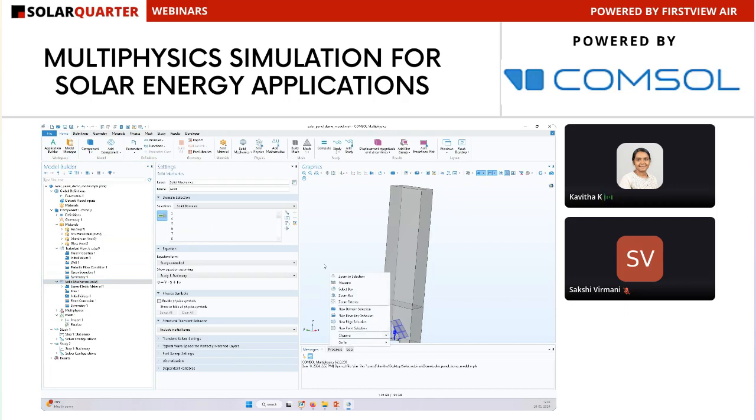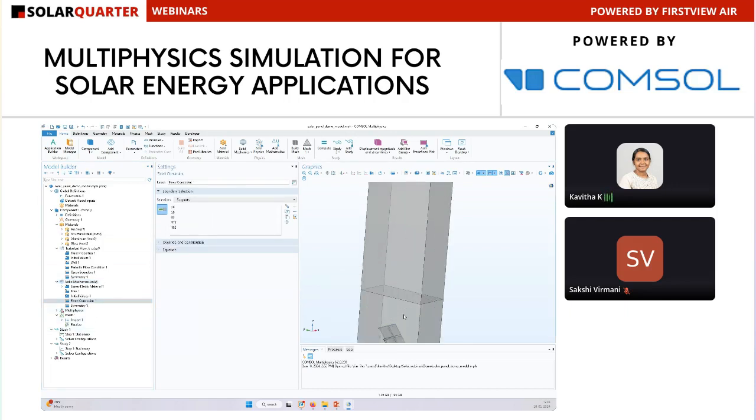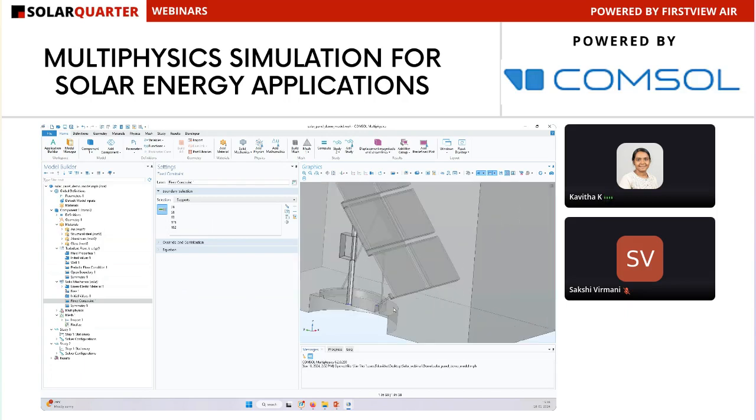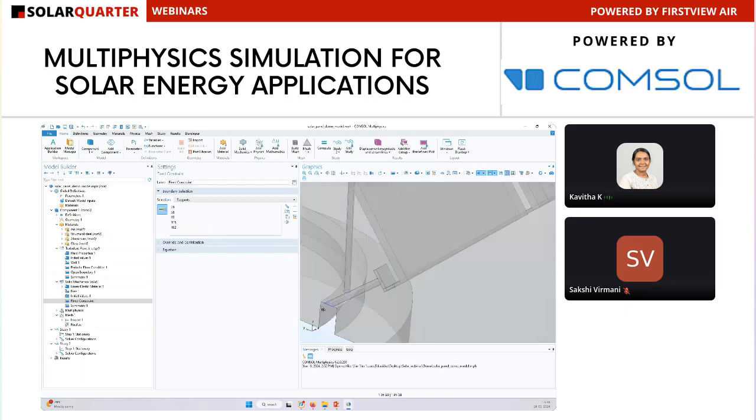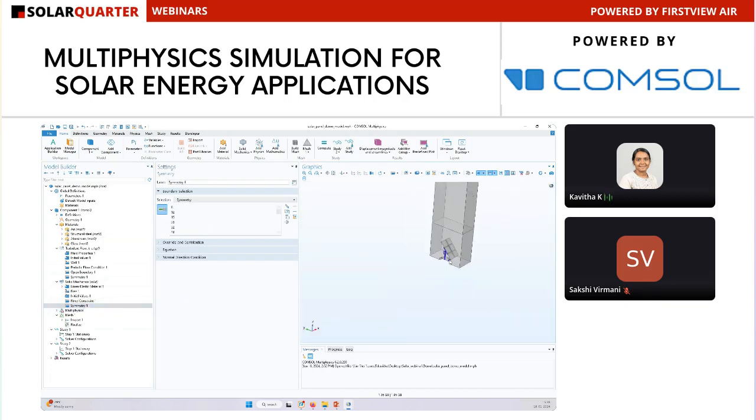So you can mention the fixed constraints. So where you want to apply the fixed constraint for the solar panel structure, say here, when you want to compute for these stresses, so where you want to have the constraints fixed. And here also you include the symmetry boundary conditions at the appropriate boundaries. Then you set up your multiphysics simulation.